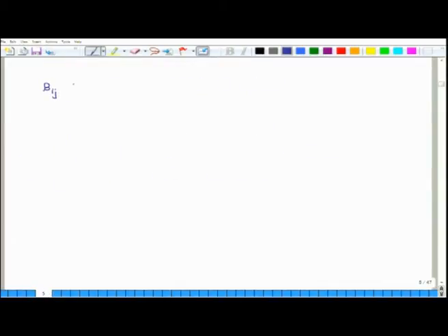So, Bij equals the sum of Qij for the kth layer times (Hk square minus Hk minus 1 square) by 2, where k is equal to 1 to n, where n is the number of layers. Now, here we have to calculate the coordinates of each layer.